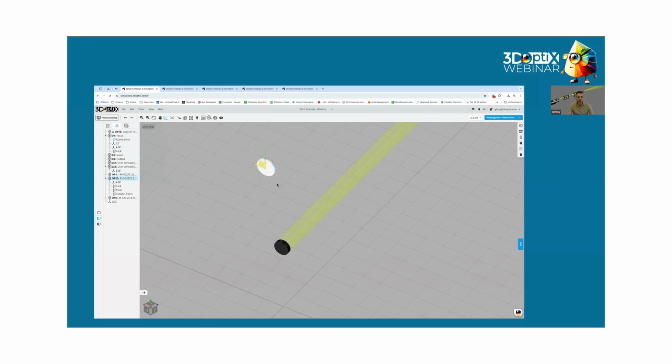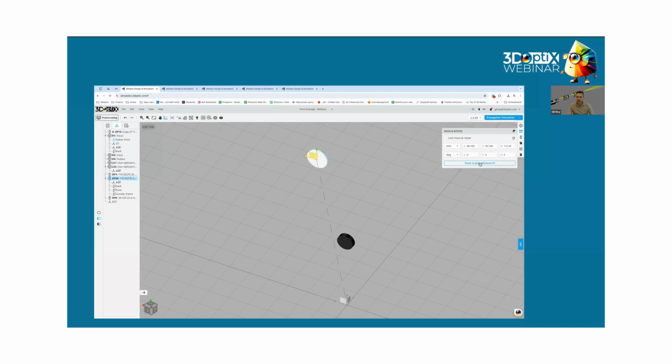Another option would work with the referencing and the coordinate system. I would go to the icon above, the turn off light, so it will be easier. Okay, turn it off. Then I would take the lens, select the move rotate, and at the bottom you can see pick a different reference system. Currently it is referencing the global coordinate system. In this case, I would like to reference this to the source. So I would change reference.